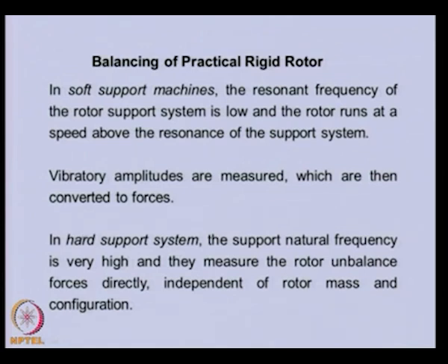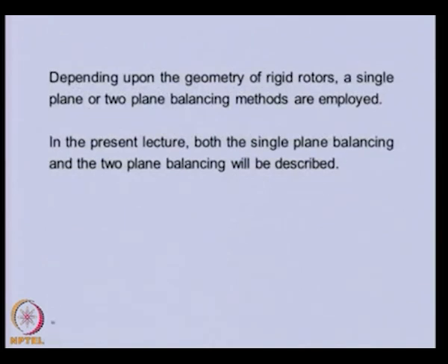There are other systems in which hard support systems are there. In this, the support natural frequencies are relatively high and they measure the rotor unbalance force directly, independent of the rotor mass and the configuration. So, depending upon the geometry of the rigid rotor, a single plane or two plane balancing method is employed. In the present lecture we will discuss both the single plane and the two plane balancing.